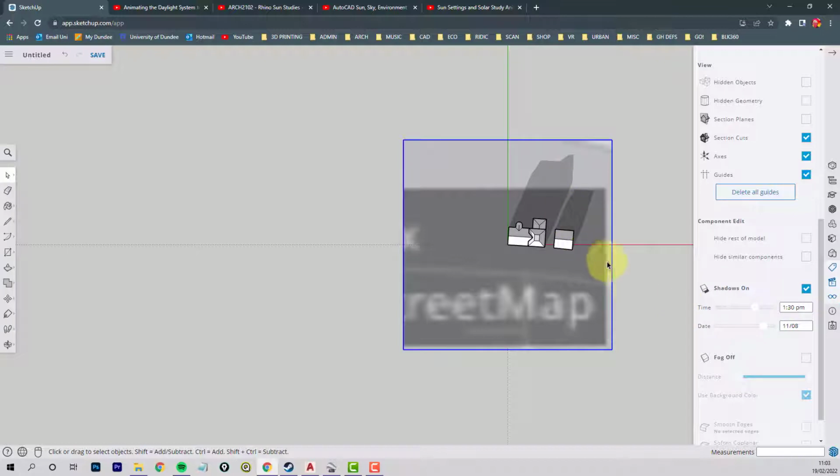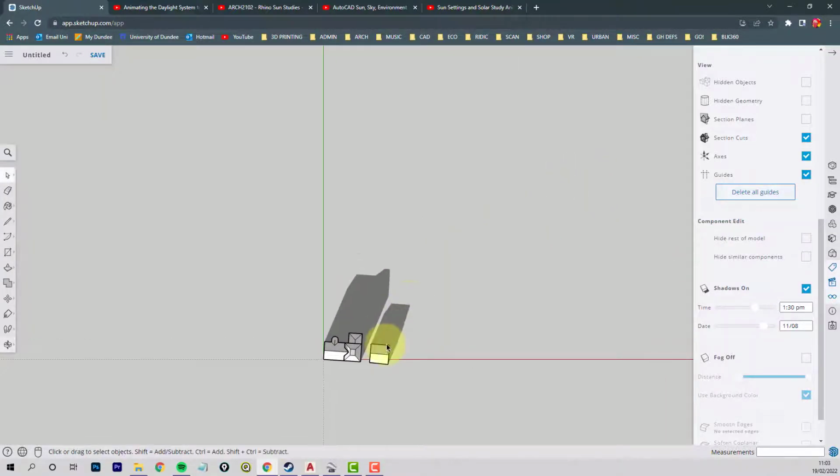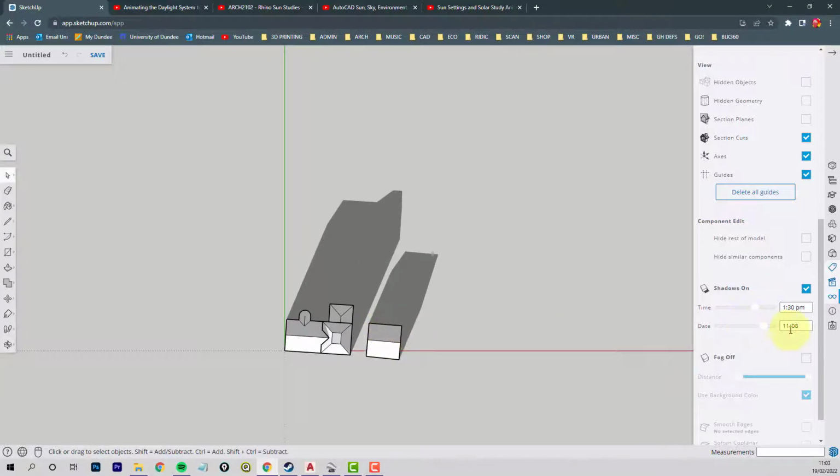Okay, so I think the shadows did get longer there. Once we brought the location in, the shadows are stretched out a heck of a lot further, because that would be the 8th of November. So no wonder the shadows are quite long. So you don't need to keep the map once you've brought it in. Okay, and then you're choosing specific dates and times. So I'm going to go for, say, June 21st, so 6/21. Okay, so the shadows will be much shorter on that day.